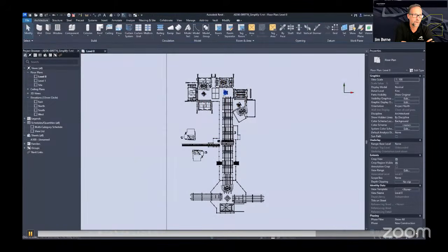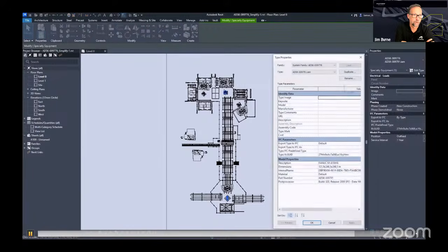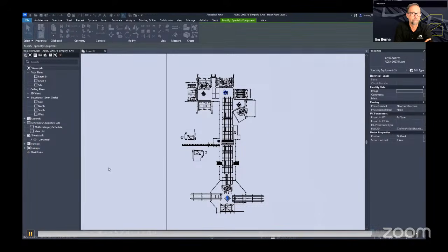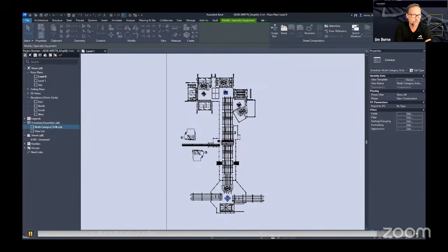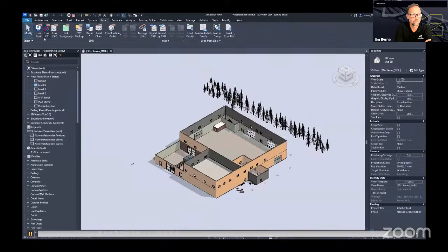And then over in Revit, here we're placing our design. You can see the metadata over on the right that we brought in from Inventor. And then you'll notice how this design can be placed inside of your Revit model based on the placement command that we used earlier to align the Inventor origin location with the Revit model.